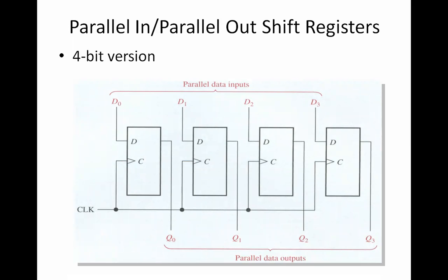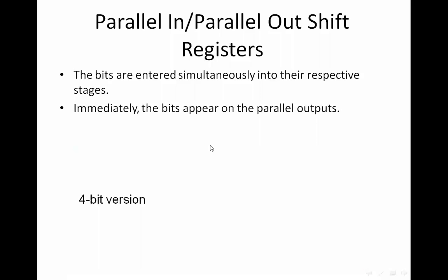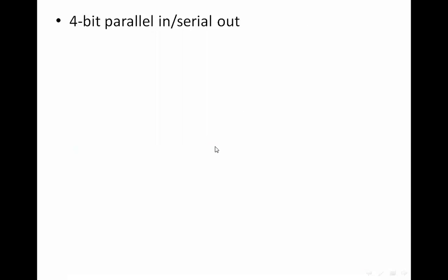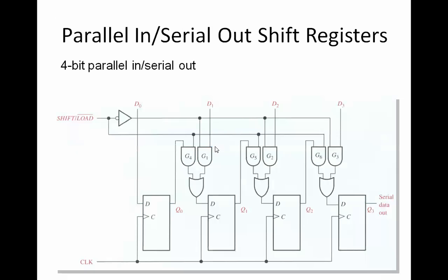So unlike previous versions, here we do not have any connections from one flip-flop to another flip-flop, right? See, your Q is just taken out. Q is not connected to another flip-flop. Let us get back and see the previous connections. So you will be able to understand that Q is actually connected to the next flip-flop via AND gate, right?